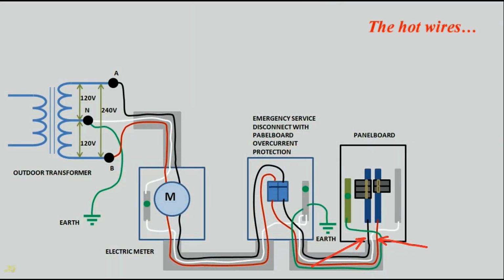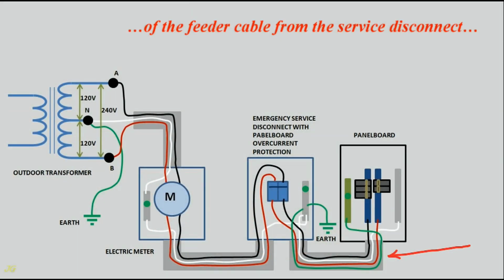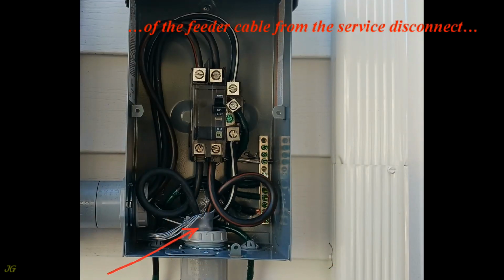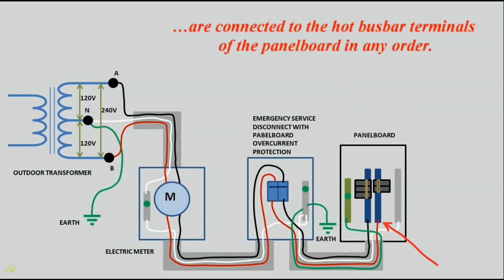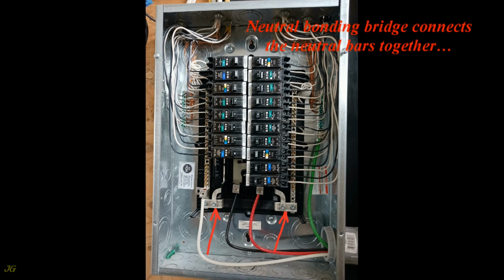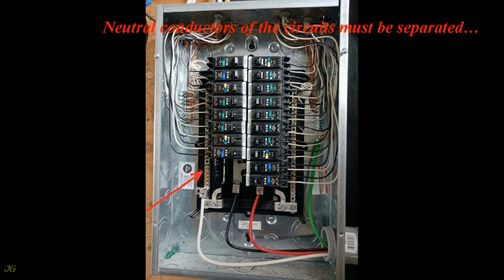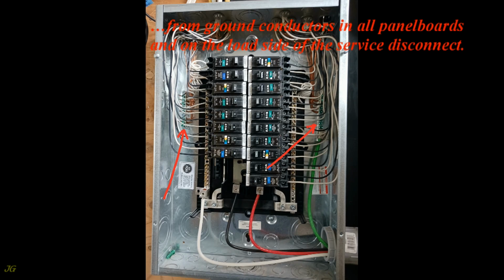The hot wires of the feeder cable from the service disconnect are connected to the hot busbar terminals of the panel board in any order. The neutral bonding bridge connects the neutral bars together, but the neutral bars are not bonded to the grounding bars and the panel board enclosure. Neutral conductors of the circuits must be separated from ground conductors in all panel boards and on the load side of the service disconnect.